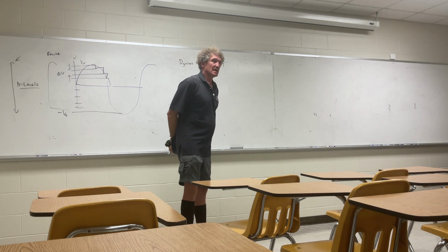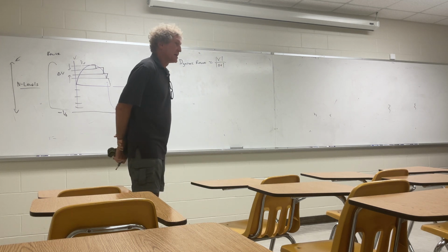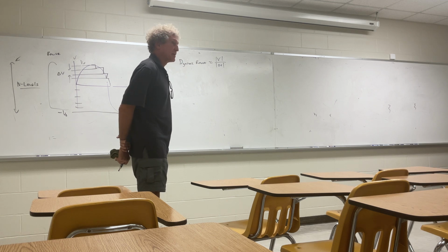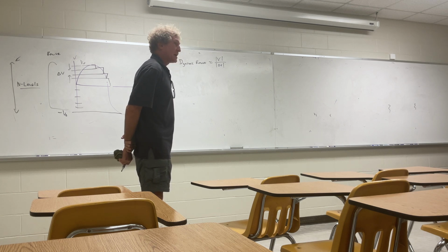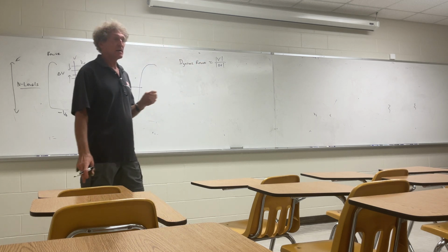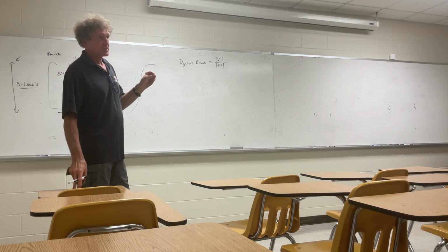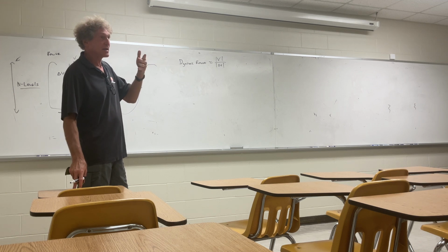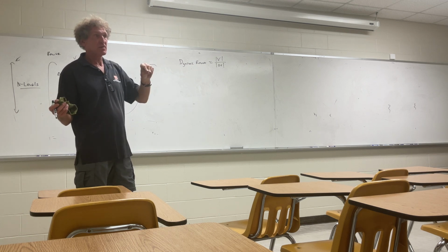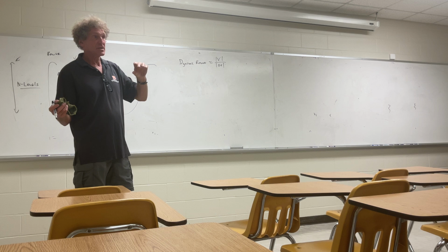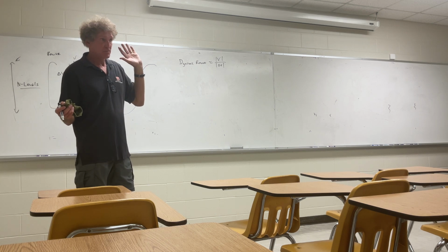And what you can see is, when you talk about dynamic range, typically it's orders and orders of magnitude. Let me give you an idea. For a voltmeter, the smallest possible increment may be 1 millivolt. That's the smallest change it can count; anything below that, you can't count it, there's too much error. So if it's 10 to the minus third, and the maximum possible voltage is 1,000,000 volts, you have 10 to the sixth over 10 to the minus third, or 10 to the ninth. That's an enormous dynamic range. It's probably an exaggeration. Are you with me on this, class?